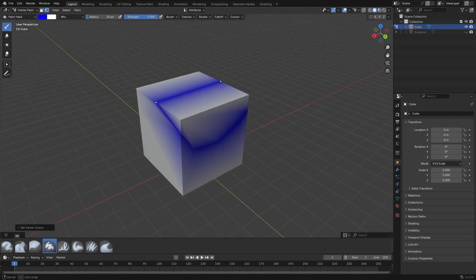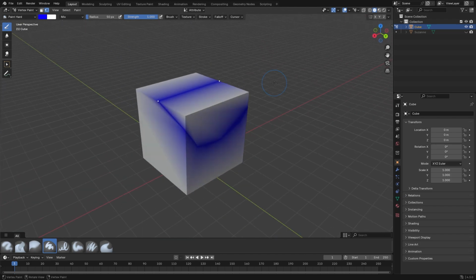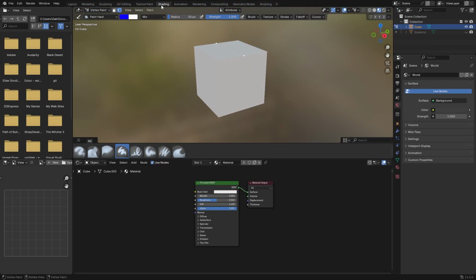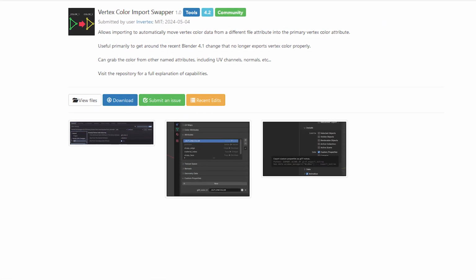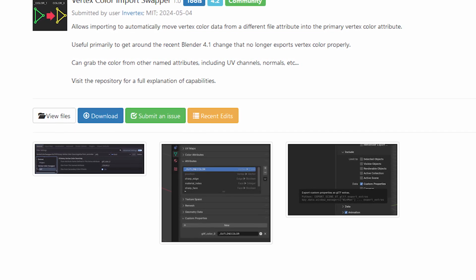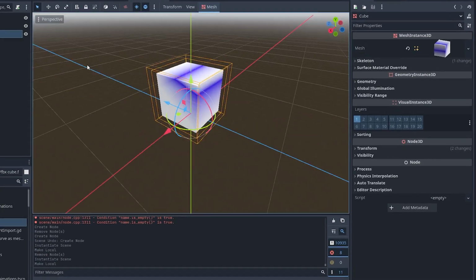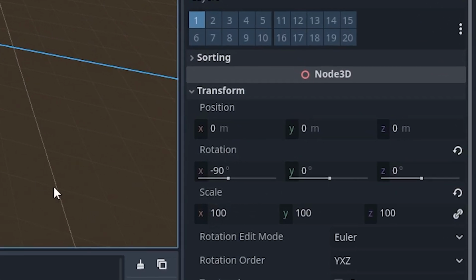And the worst news is actually not that. The worst news is that the GLB format doesn't transfer vertex colors out of the box. I kid you not, this doesn't work, they straight up disappear. So you either need to invent some actual material to use your vertex color as input for Blender to agree to export them, or you need to install some special Godot add-on for fixing that problem and then export vertex color as a separate meta attribute, and only then touch it in Godot. I am good, thanks. You can escape this by exporting as FBX, but the FBX format has a bunch of other problems that I won't even go into. If you are interested, you can ask in comments or in Discord.